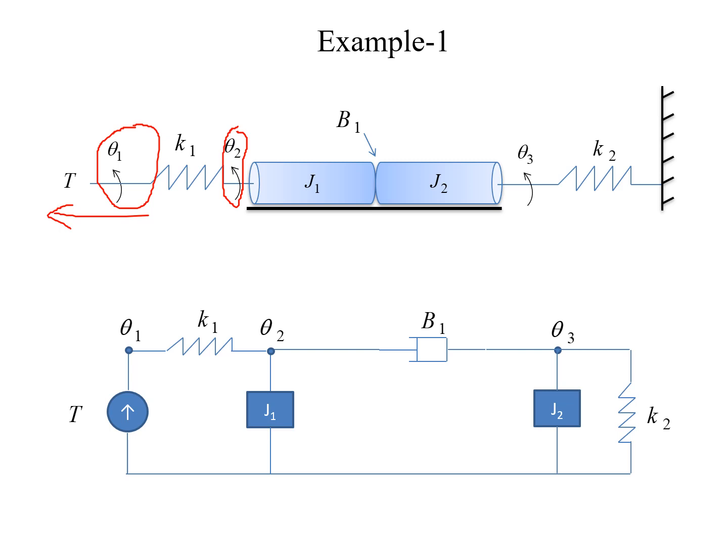And the angular displacement that is experienced by J1 is nothing but equal to theta2, and the angular displacement experienced by J2 is nothing but equal to theta3. So here we have a displacement which is represented as theta3, and since the spring with the coefficient K2 is connected to a fixed wall, here we will not have any displacement. So totally, if you can observe here, we have three displacements, theta1, theta2 and theta3.